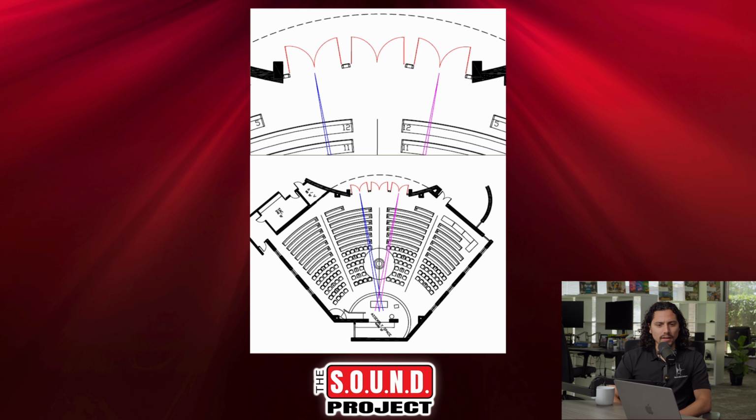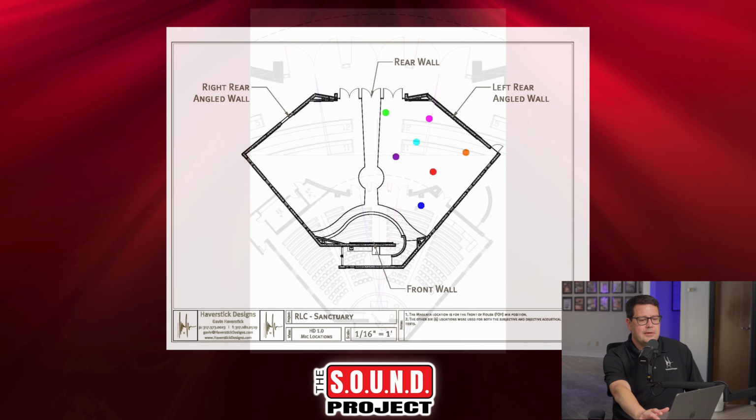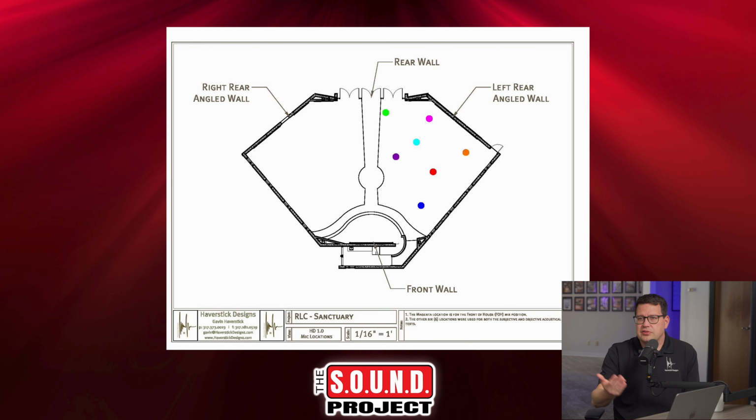And so did you end up flattening out those doors? Yeah. Yep. Cool. So the next thing here, we went in after construction was complete because we had done some models of the room and come up with an acoustical treatment plan, but we wanted to test the real world conditions. So since the room is very symmetrical, we ended up testing 7 spots on the right hand side of the room here, and those are all color coded. So in our report, we can show frequency response and impulse data for that.